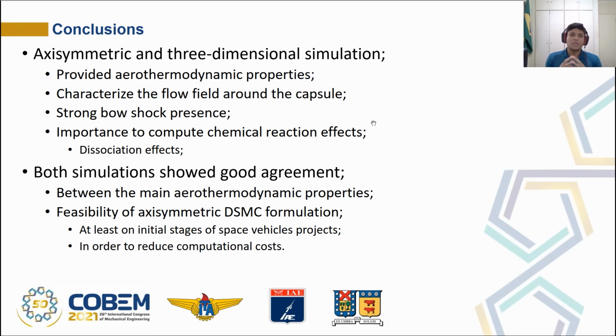We can see two main conclusions. The first is that the axisymmetric and the 3D simulations provided aerodynamic properties with good agreement between them. Both of them helped to characterize the flow around the capsule, where we noted the presence of a strong bow shock wave.